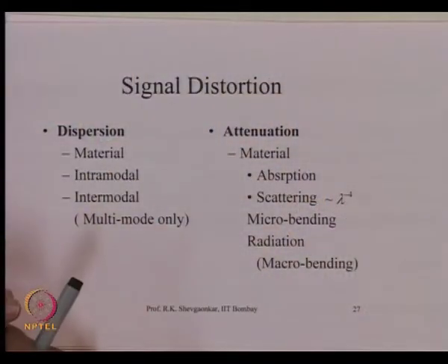However, you will note that the dispersion phenomenon is rather a weak phenomenon. What that means is that unless we want a very accurate value of dispersion, one can assume that each of these dispersions can be calculated independent of each other. What I mean by that is that when I calculate material dispersion, I assume that the waveguide dispersion is not present or is negligibly small.